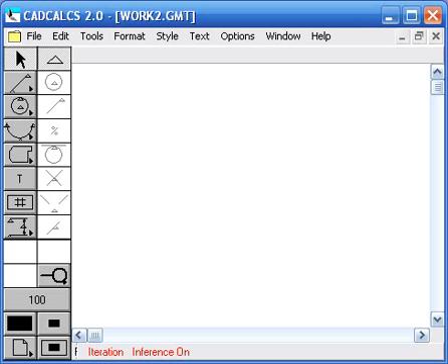So you can goal seek any geometry which affects that measured or calculated value automatically to satisfy design challenges that benefit from optimization against stated shape, position, and fit design criteria. The GoalSeek capability works on the lengths of lines, the angle of lines, and radius of circles. These are the three things that you can goal seek. You can goal seek the angle of any line, the length of the line, and the radius of a circle.